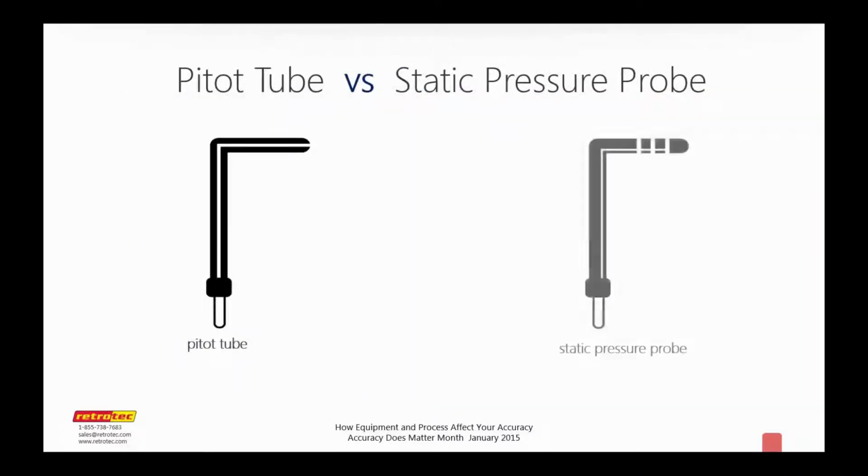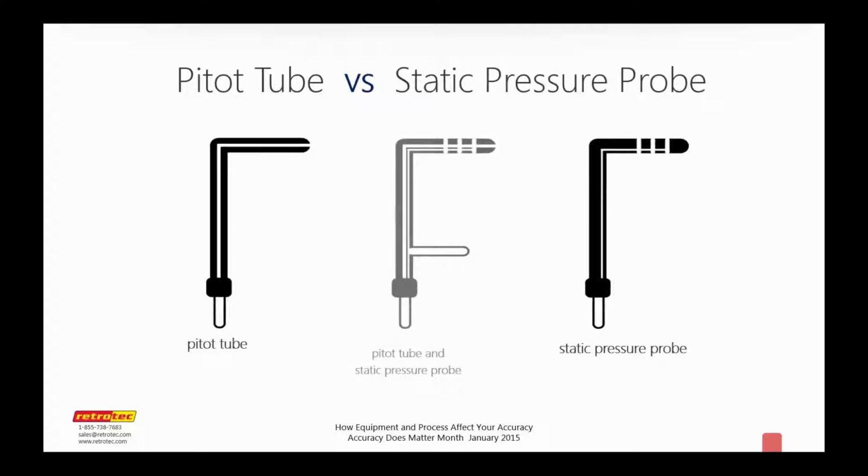So same sort of idea, same sort of concept, but applied to duct testing. When we're testing a duct, we are going to reference the inside of the home, or technically the outdoors, right? Pressures from the outdoors, because we're going to keep a door to the outside or a window to the outside open. But the input tube is going to be somewhere along that duct, usually right inside the nearest supply register.